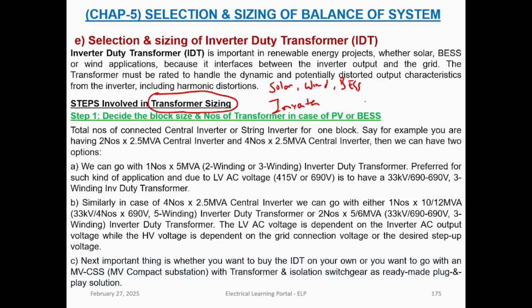The challenge of transformer sizing is predominantly when we are doing any kind of industrial plants. In a plant, based on that same Excel sheet which we studied in chapter 1, you need to decide the overall kW or kVA of that particular distribution transformer or power transformer. You also need to consider future addition which could happen, design margins, and a lot of other things. Thus there is some kind of transformer sizing which needs to be done in industry, because there are a number of motor loads and different motor startings at different points of time, so motor starting also needs to be taken into consideration.